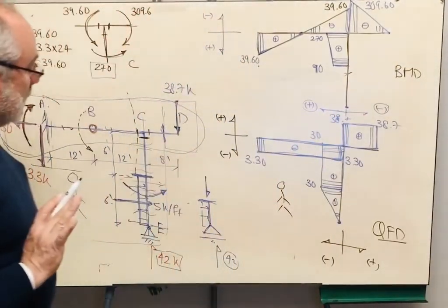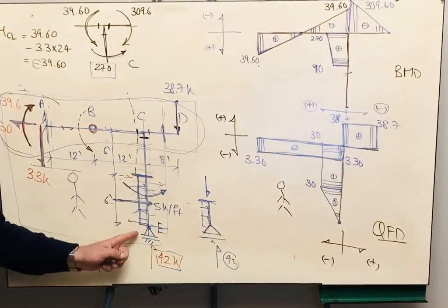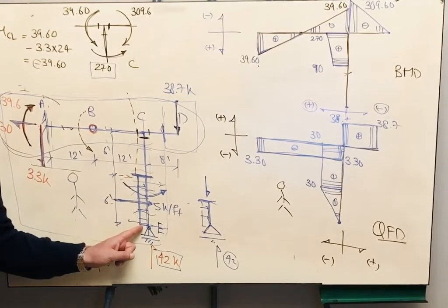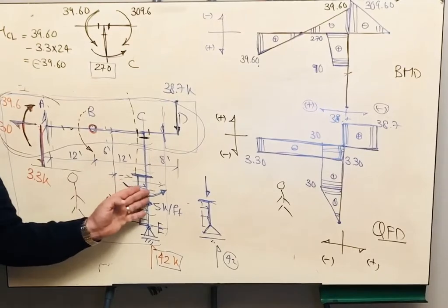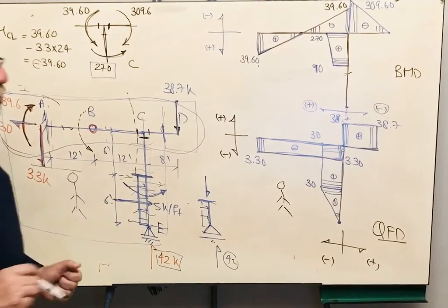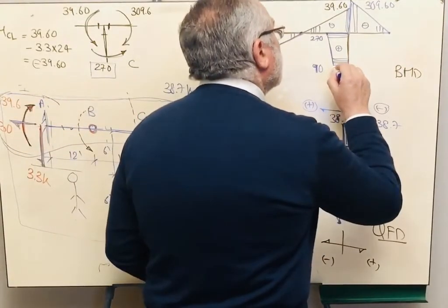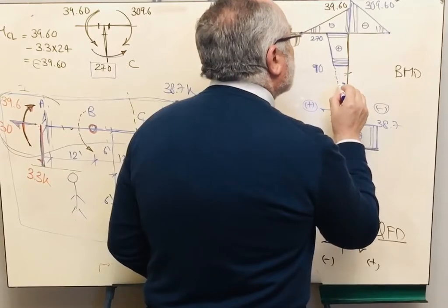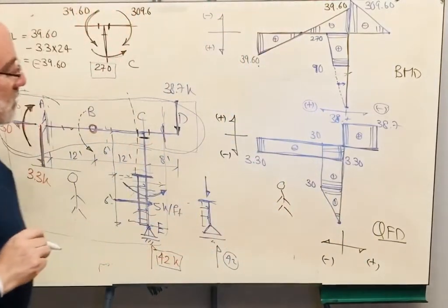Again, now for this portion, we knew the bending moment at the beginning, and we knew the bending moment at the end, and we are having distributed load. Again, we are back to the method of superposition. So we are going to connect them with a straight line, and then we are going to suspend a parabola. What is the magnitude of this parabola?